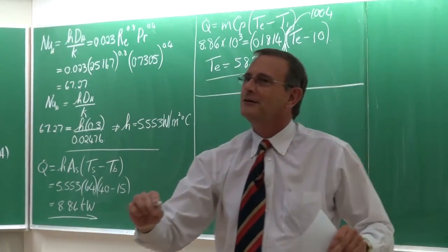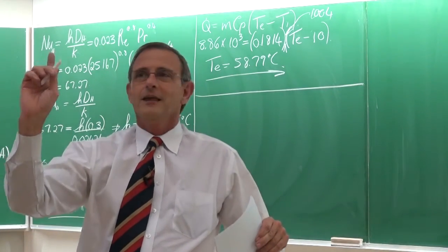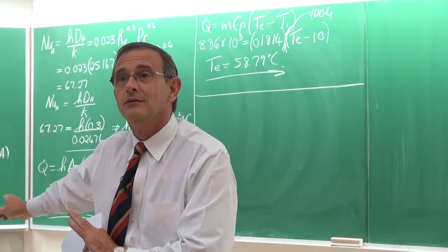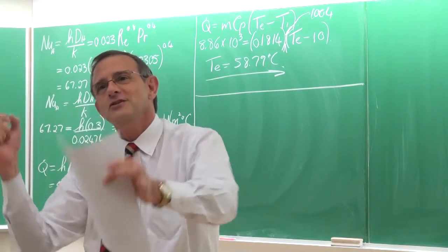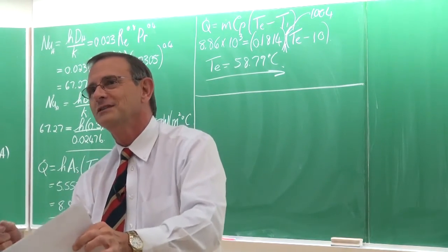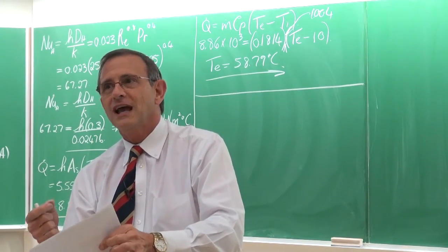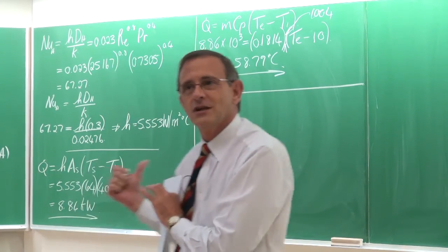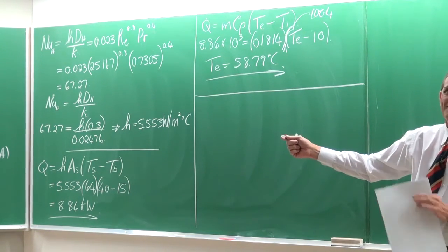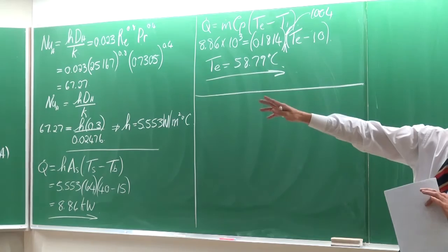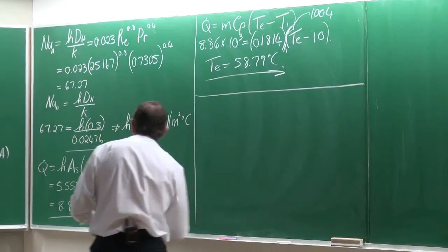Oh. You should use the log mean temperature difference. Ha, yes. Thank you. It's all wrong. It's a trap. It's the classical trap. I've spent theory, and I've explained to you why it is important that you cannot do it. You've got a constant wall temperature, you need to use the LMTD. Otherwise, this is going to happen. Look at this outlet temperature. I mean, it can't even be. Wall temperature is 40. How is it possible? Even although I've made maybe a mistake here. So, ladies and gentlemen, this is all wrong.